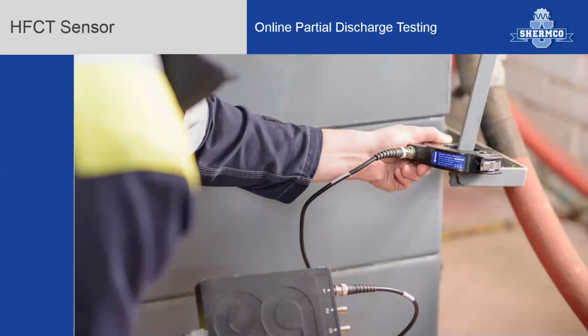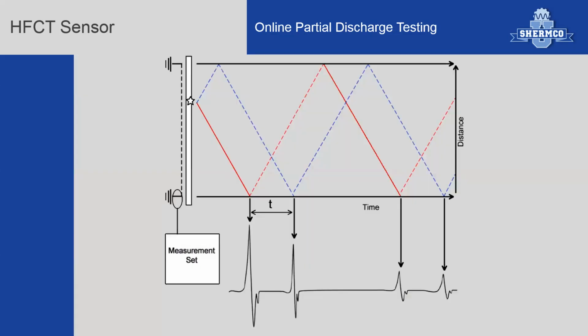Also, the high frequency CT lends itself to the ability of helping us to locate the location of partial discharge, for instance, in cables. Here we show an example in this slide where we have a cable section. The CT is clamped around the concentric neutral of the cable. And if a PD event occurs, for instance, where the little star is in my picture, a current pulse is going to launch in two directions.